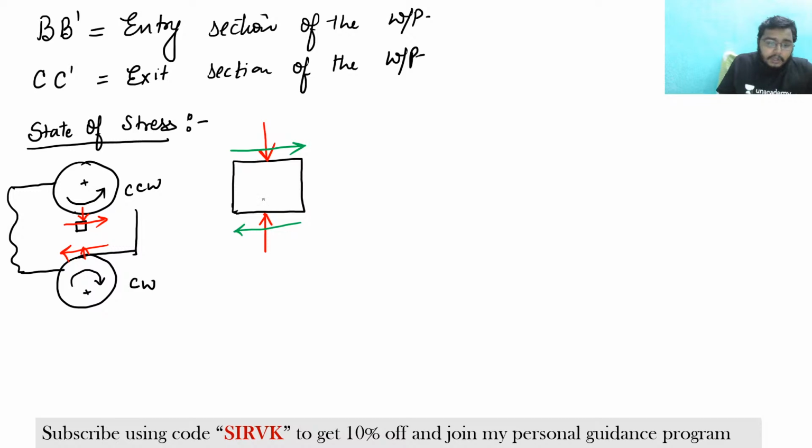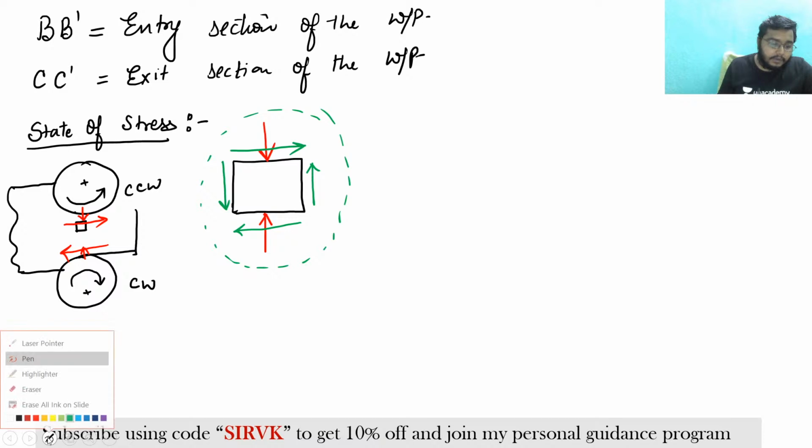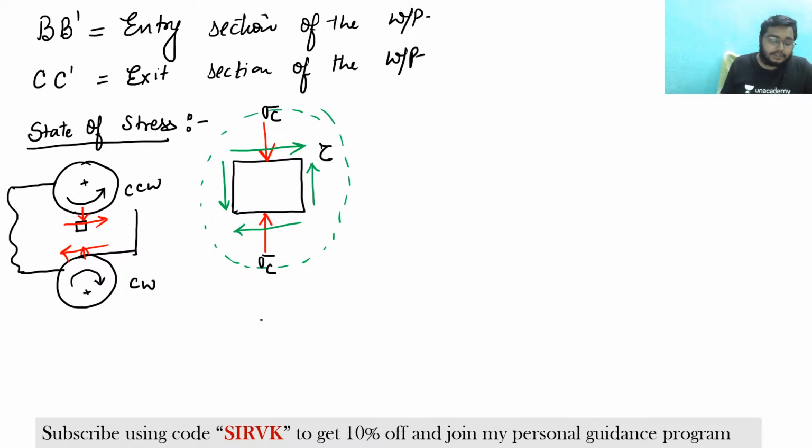Now there is a shear force acting in this direction, so to complement this shear, a complementary shear stress would be acting in this direction. Fine. So this is the state of stress. This would be compressive stress, and this would be shear stress that is acting. So the state of stress is compression plus shear.